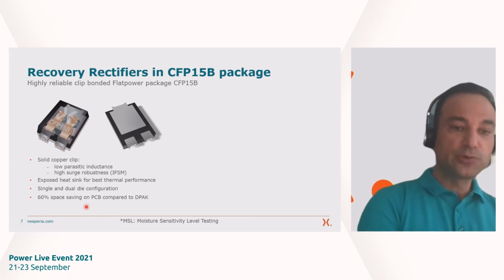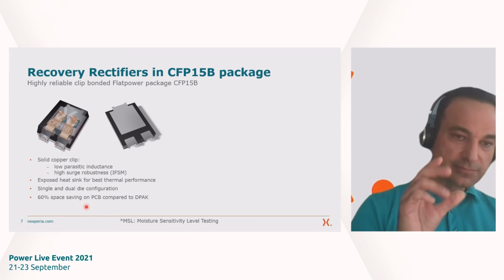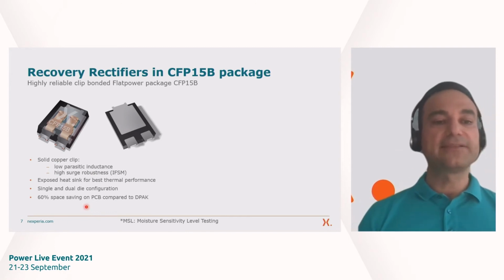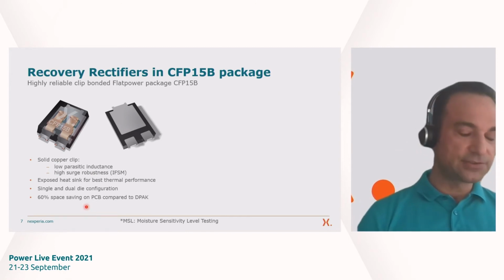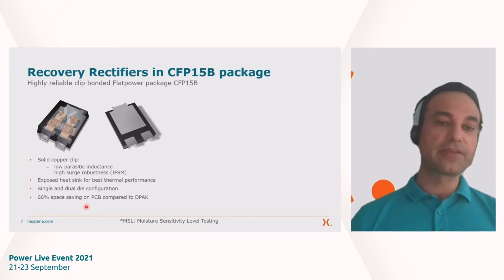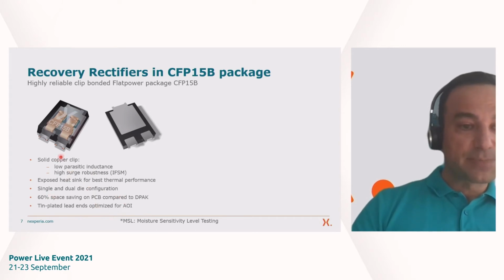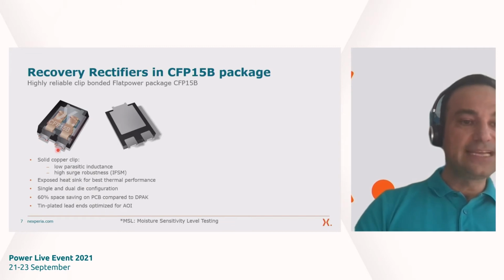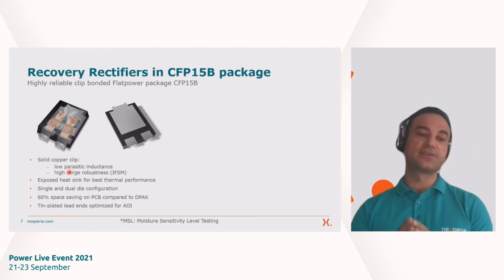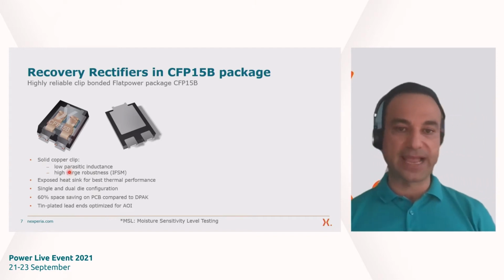Compared to a classical DPAK package, you can save up to 60% space on the PCB. I think this is quite remarkable. And last but not least, we have tin plated lead ends. And this allows for an optimized automatic optical inspection from every possible angle.